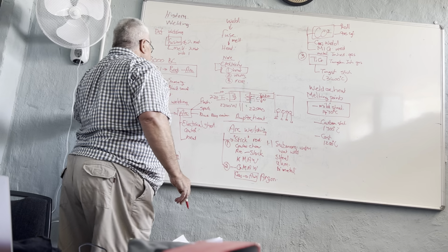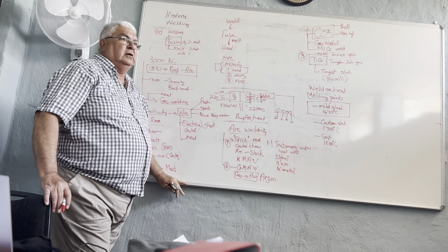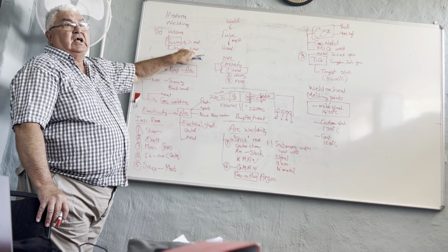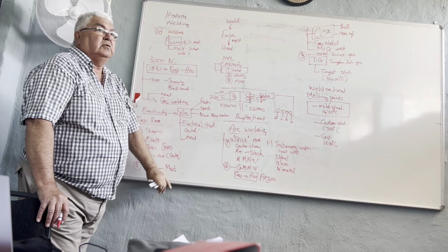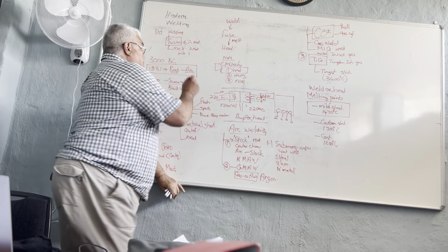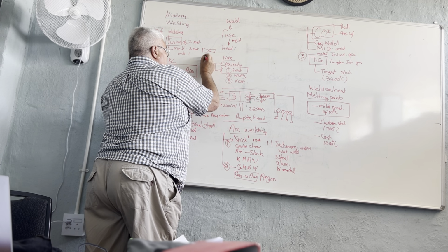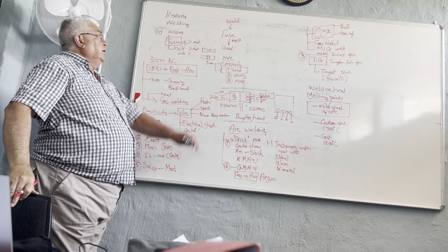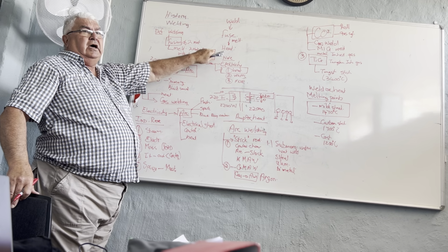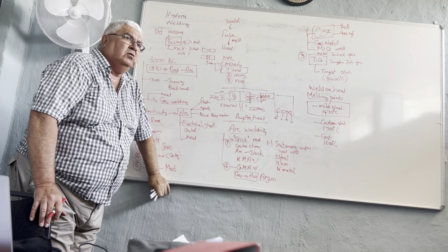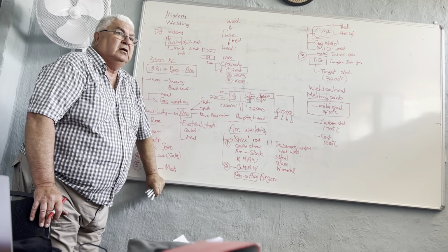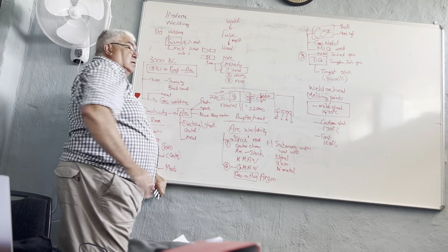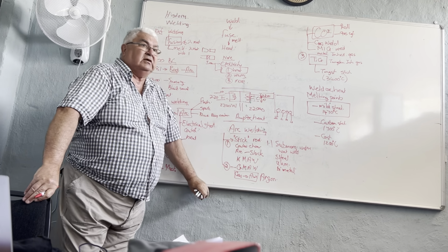Remember when I said that I want to fuse them, melt two materials into one. I want to have the same characteristics of the material. If there are two different types of material, you're not mixing them into one material. For instance, if I've got iron and weld that to iron, the fusion layer here is iron. But if this is high carbon and that is low carbon iron, what is this mix? I don't know. It's not as strong as that, it's maybe not stronger than that one. It's already ready to break. Welding is limited to the same material, but we have special rods now that can do bimetals.